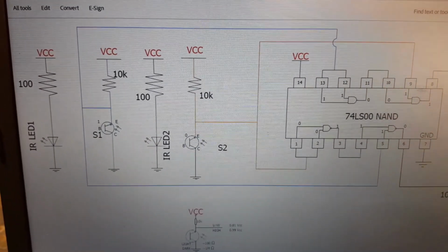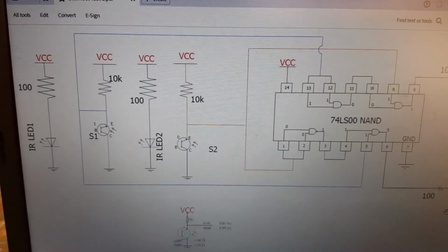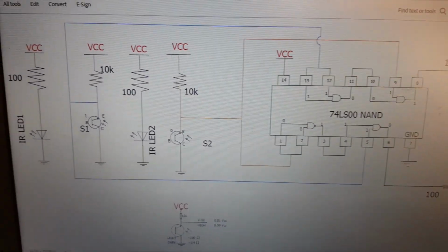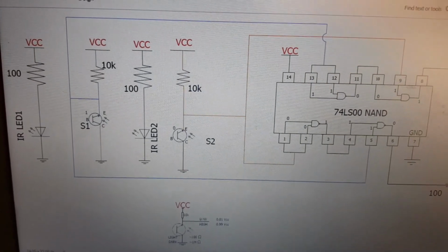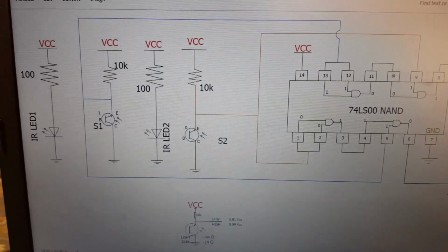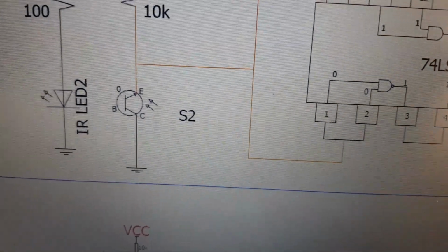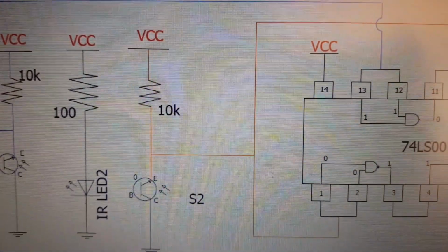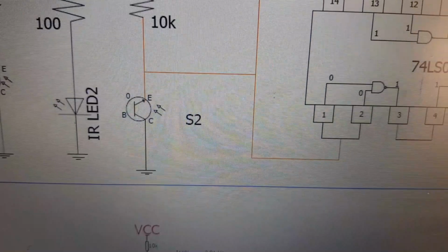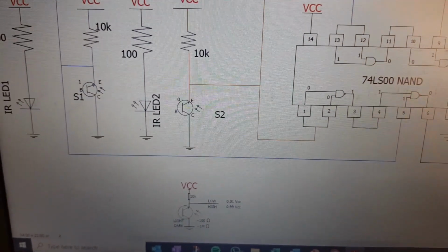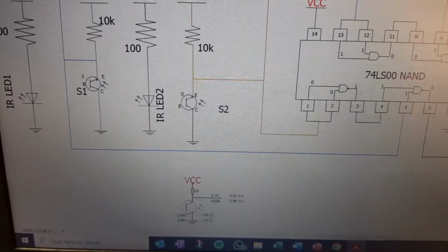You'll also notice that if you look at the way you normally connect an LED, the photosensor has to be connected in reverse. Otherwise, you will not get a result out, in this case with the BeamBot. And if you have your diagram with you, you can see that you must connect your emitter to your VCC and your collector must be connected to ground.